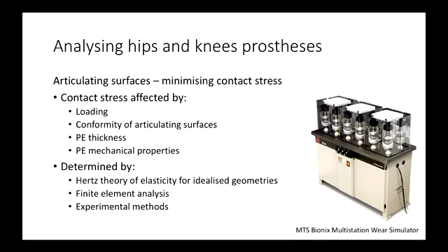So how do we determine contact stress? We can do a Hertzian analysis. So there are analytical solutions. The other way is finite element analysis. The thing is with finite element analysis, it's very hard to get contact working reliably. You get predictions of contact stress, but you don't always believe what you get. So the analytical calculations are reasonably reliable.